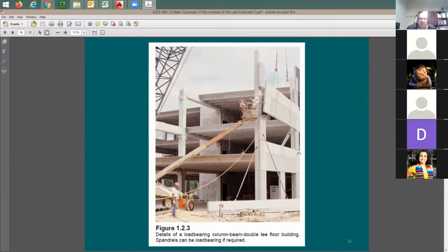In some buildings, when you have a structural steel building, and let's say it's going up maybe 5-6 stories, you don't really want to do it out of precast concrete. And then you have a subterranean parking structure, like 3 or 4 levels. I have designed one of these buildings, and we really had to complete the whole thing out of structural steel. So the 3 parking levels were made out of structural steel. For the concrete deck, we made it 4.5-inch hard rock concrete. I mean, it should perform well.